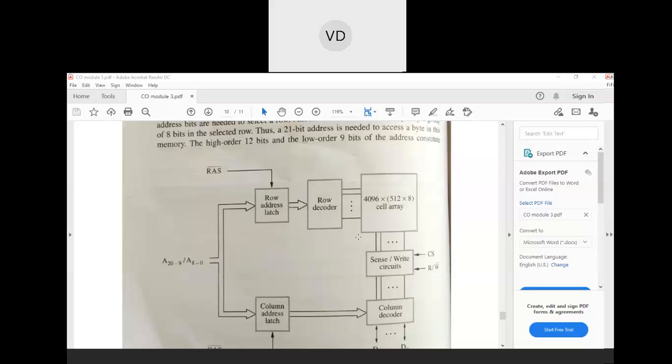If we start sequentially, from first group, second group, third group, fourth group, like this: once the row address is given, first group of column, same row address, second group of column, same row address, third group of column. Like this we go on refreshing sequentially. For that we are going to use a counter here, a row column address counter, in which the sequential groups will be selected automatically. So for the same row address, first group, then for the same row address, second group.